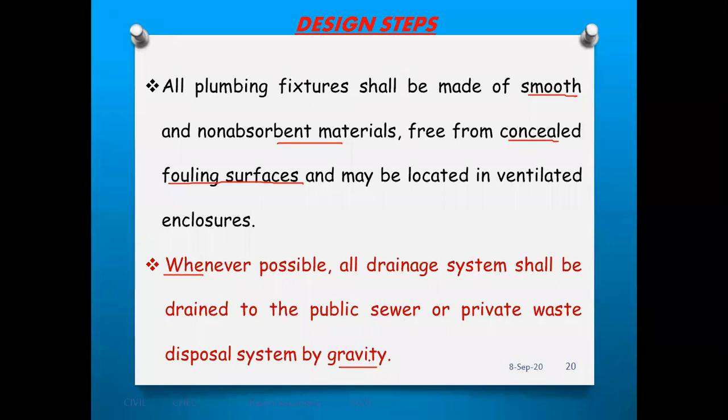So what is the solution for that? Generally if we design in gravity type, there is no need of using pumps. So that's what the rule is saying. Whenever possible, all drainage systems shall be drained to the public sewer or private waste disposal system. So whenever possible, without storing, all drainage systems shall be drained to the public main.